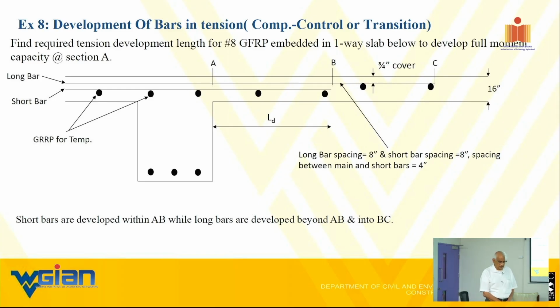In theory, I don't know how much you appreciate, if I have a bottle, and I do a compression test, this is going to fail in a certain mode. If I fill this with sand and then wrap it, in theory, when I do the compression test, the load is infinity. Of course, that doesn't happen.